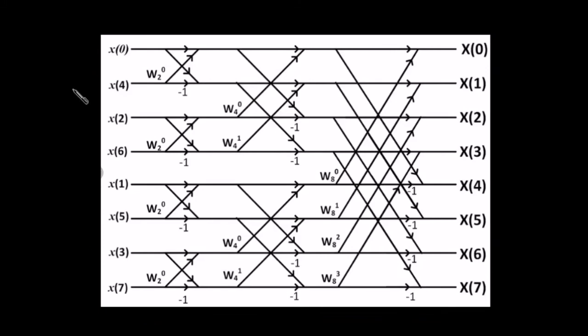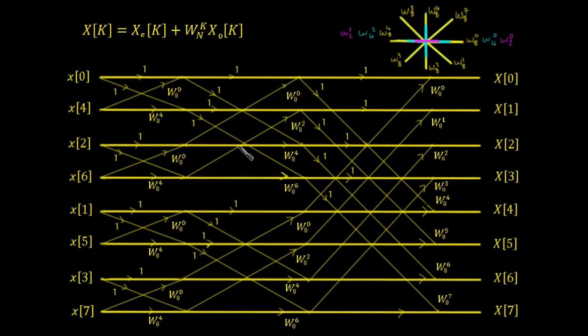So here's the final simplified butterfly diagram here, and you can see that the values of n down this lot here are a value of 2, and down this lot are the value of 4, and down this lot the value of 8. You'll also see that some of them have been replaced by -1, and you can see that up here because our W48 or W24 and W12, these here all have a value of -1.